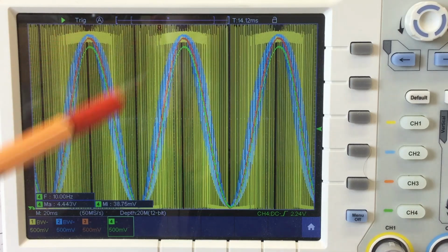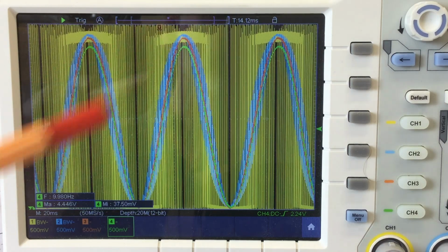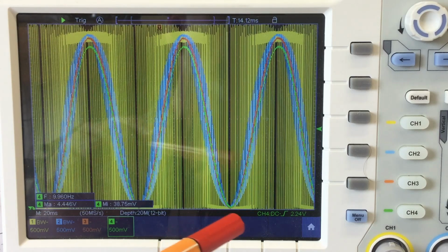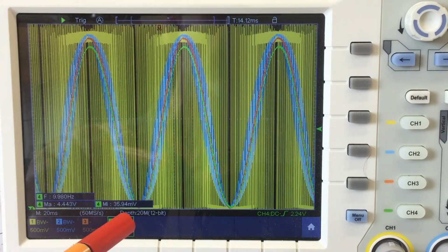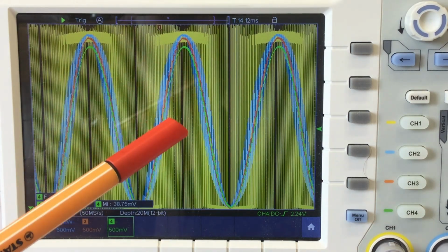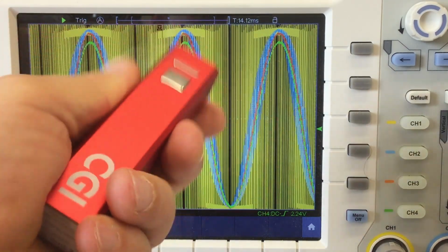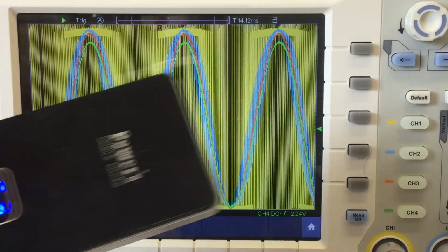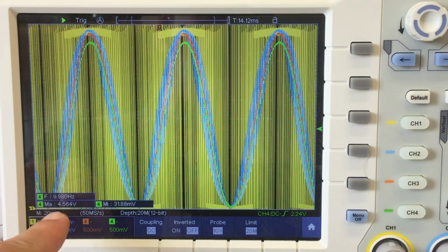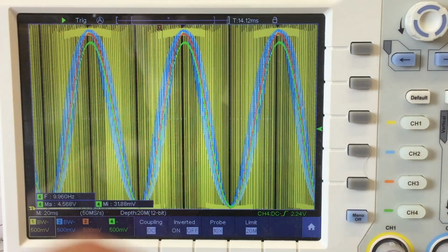And the real world strikes on another front too. See, the peak voltage of my output is 4.45 volts. And it does not go down to quite 0 volts. It stays at a few dozen millivolts. But that's not all. I just swapped the USB power supply of my Arduino, that was the old one, with another one. And you see the output voltage is now 4.57 volts. So it changed.